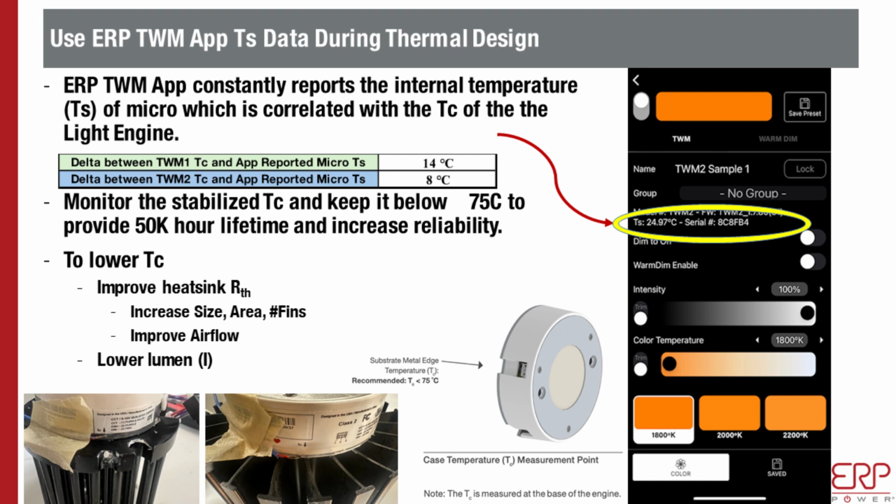If you see these are getting close, or there's a very, very small delta between them, that means your thermal design or heat conductivity is not done right. Either you don't have a good thermal contact from the module to the heatsink, or there is some sort of insulator there that is preventing the heat from getting out or being coupled to the heatsink. So that'd be a good indication.